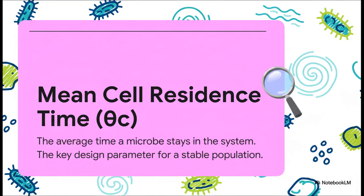Well, the answer is this absolutely brilliant engineering control parameter called the mean cell residence time, or theta C. This has nothing to do with how long the water is in the tank. It's all about the average age of our microbial workforce. It is the single most important lever we can pull to control the entire biological system.